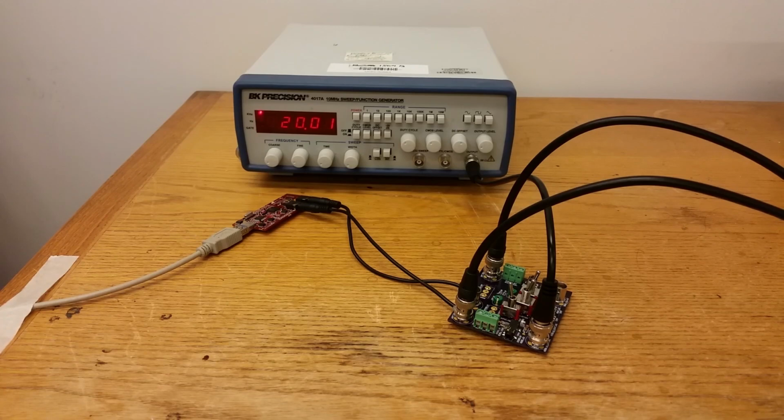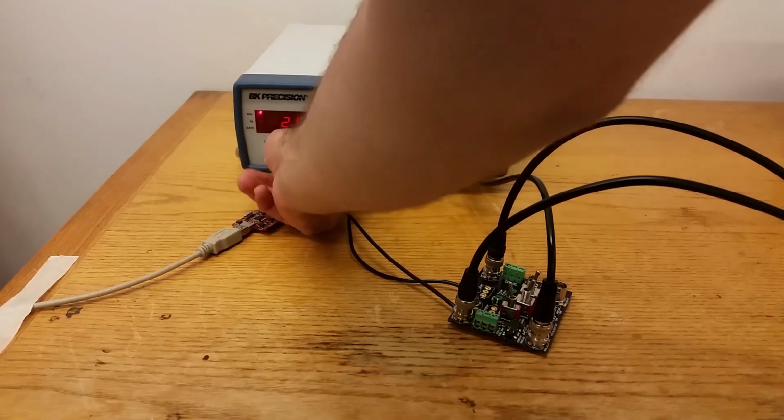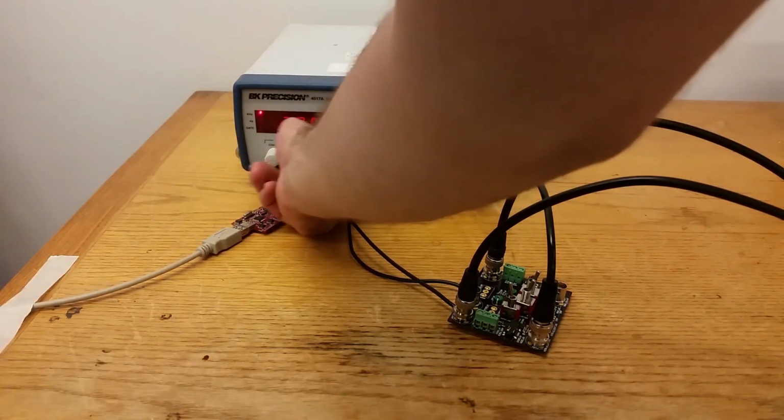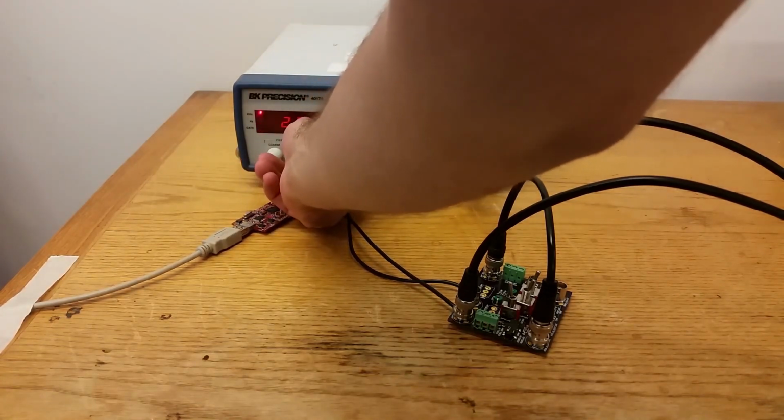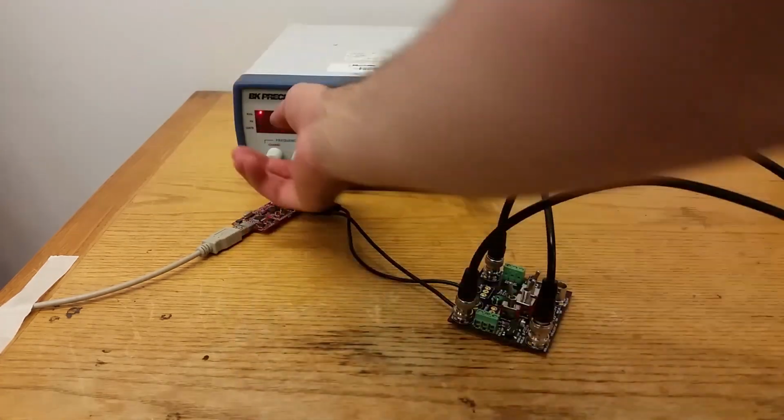For this lab, we're going to change our signal from 20 kilohertz input. We're also going to show 10 kilohertz and 5 kilohertz. So let's go ahead and change our signal generator to 10 kilohertz now. We're going to change the coarse adjustment frequency, but first we'll set the fine adjustment to the middle, which will give us some room to play on either side.